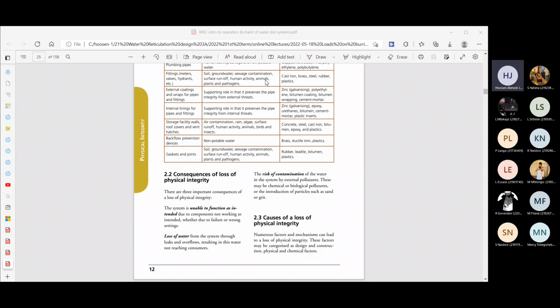Any other queries? For the embankment conditions and trench conditions, what's the value for gamma? Gamma is the unit weight of the soil. You would either get that from geotechnical conditions or you'd have to make an estimate. Unit weight of soil varies.